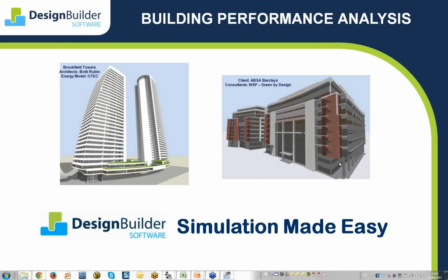There's a question here asking about what happens to the interior wall volume, 10-20 centimeters thickness of wall, when we import the Revit model to DesignBuilder. With the latest version of DesignBuilder, we use the surface mechanism within Revit, which means that we import the external surface dimensions.